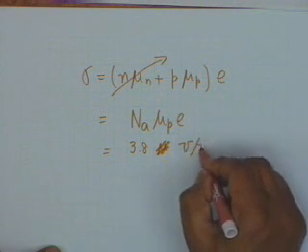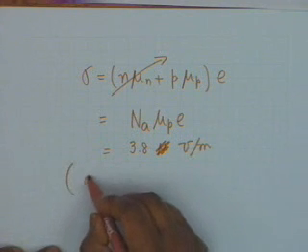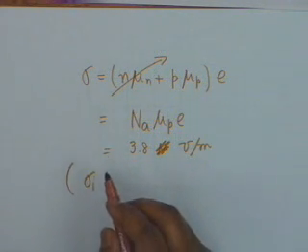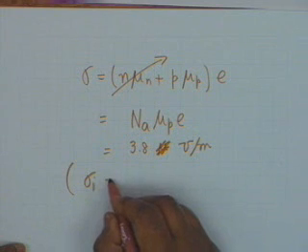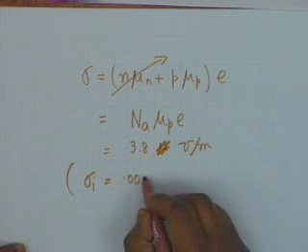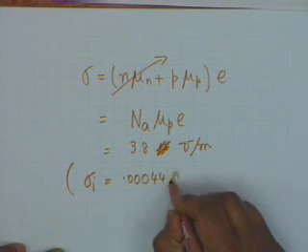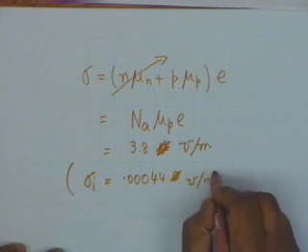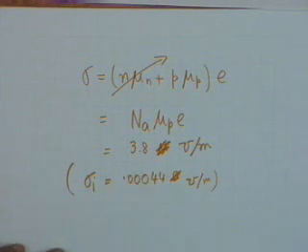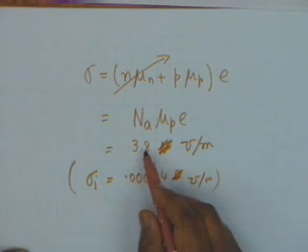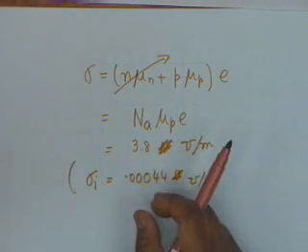And this calculates out to 3.8 mho per meter. If you compare this with sigma_i, the intrinsic conductivity is of the order of 0.0004 mho per meter. You can see how many times the conductivity has increased, even with a small amount of doping, which amounts to only 1 atom in 10 to the 7. And this is the main reason why semiconductors are so important.